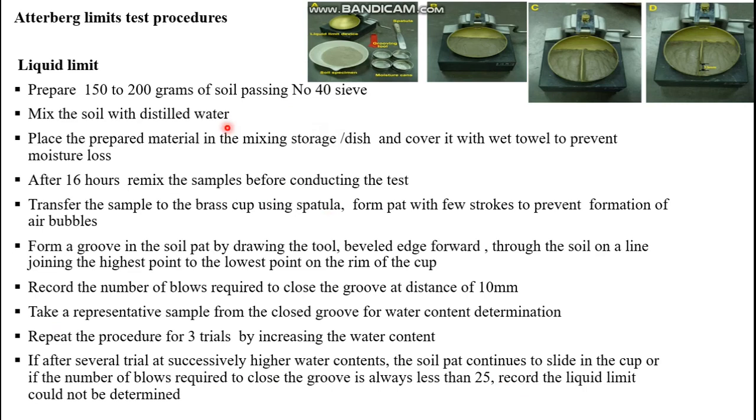So how can we determine Atterberg limits? Atterberg limits are determined using the AASHTO manual. There are a series of procedures, and the important procedures are laid out below. First, you need important tools such as the Casagrande apparatus, a soil mixing pan, moisture cans for determining water content, a spatula for mixing the soil sample, and a grooving tool for making a groove.